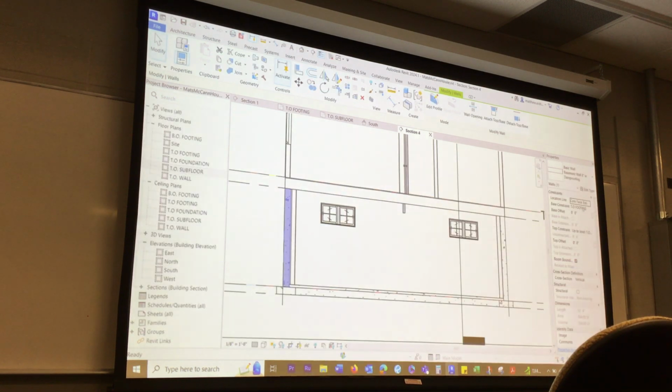The constraints were pretty good. Most people seem to understand the base constraint, if you need to offset it, and the top constraint. Most of you were pretty good that way, so that was good to see. I think that's probably because you've been through estimating, right, and you understand that a little bit. But just where you're drawing to, that's more of a Revit kind of tool thing. When you've got that complicated exterior wall assembly, what part of it do I want to line up to where? That's what you really need to know.